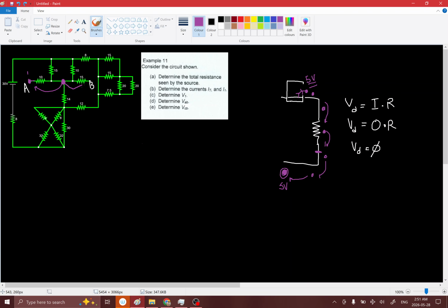So over here would be the same situation with B. The electrons are coming down, whatever the voltage is at this area here. Whatever the voltage is here is going to be the exact same voltage as over here. That's because these points are connected simply through a wire, which means that there's no voltage drop between these 2 points. And so the voltage is going to be exactly the same between these 2 points. So any voltage that's here is going to be the same voltage as here.